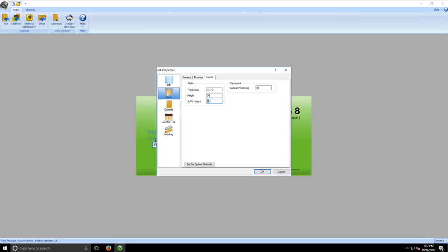Now, if you do that with a 4-inch tall crown molding, you go from 4 inches on one side down to 3 inches on the other. That's not too bad. You're not going to notice that. You've only eaten up 25% rather than 100% of the molding. That's going to help you in installation. So that's my spiel on the soffit height.